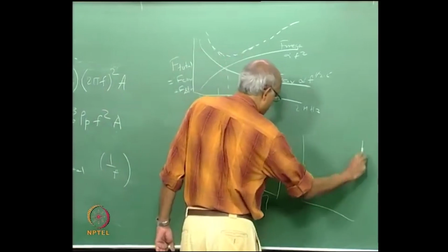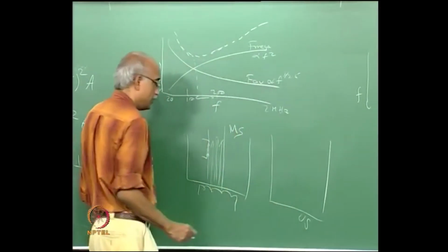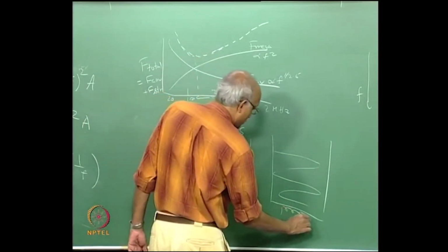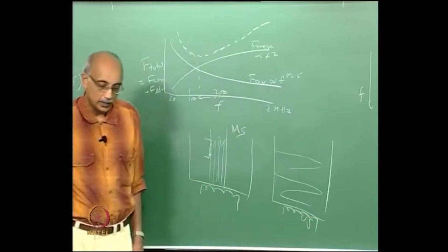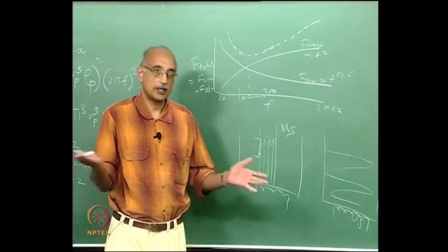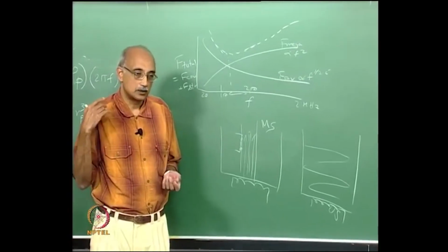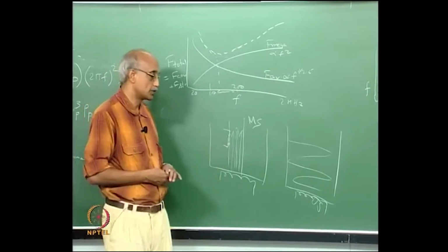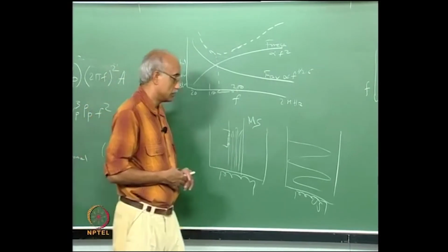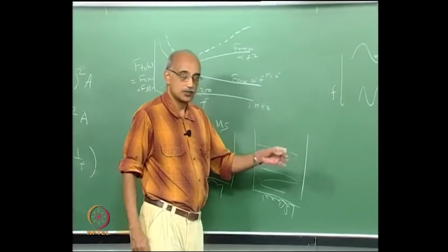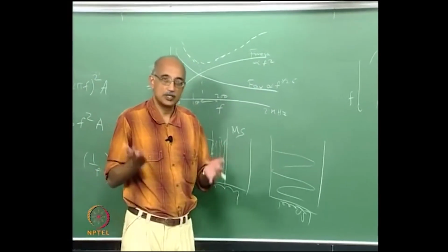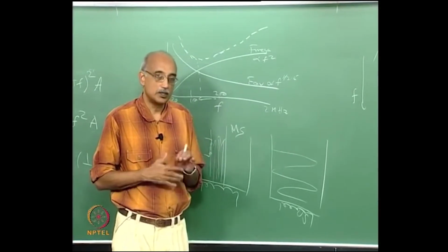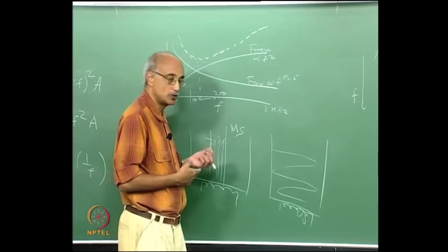If you look at an ultrasonic tank, the field is absolutely uniform. Even if the transducer is mounted at the bottom, the way that cavitation happens is inherently chaotic. It's unpredictable, it's not repeatable or reproducible, but it is uniform. And so, you can essentially place your component or surface anywhere in this tank and you will get virtually the same energy of particle removal. That is a huge benefit, particularly in manufacturing lines where you typically do not clean one surface